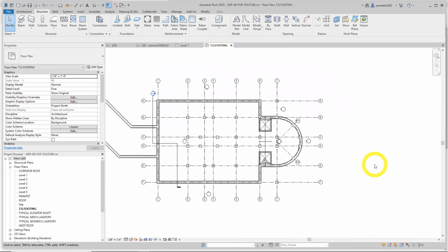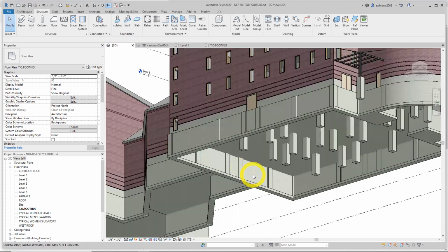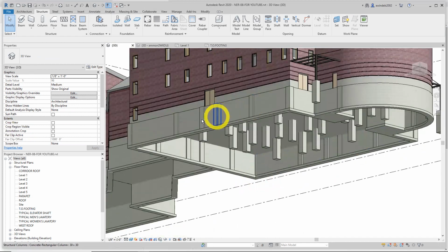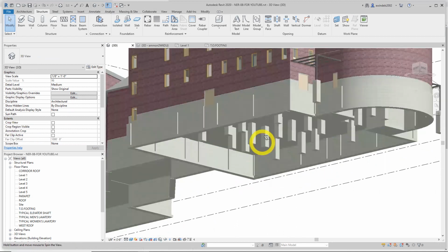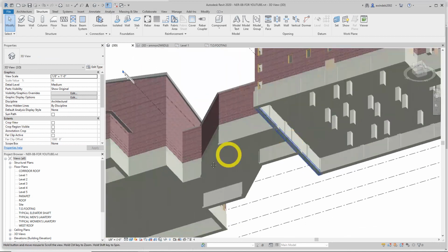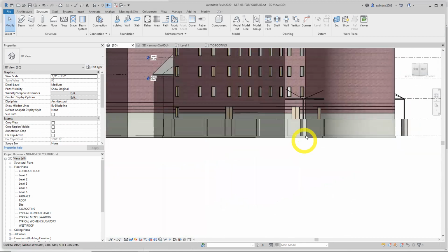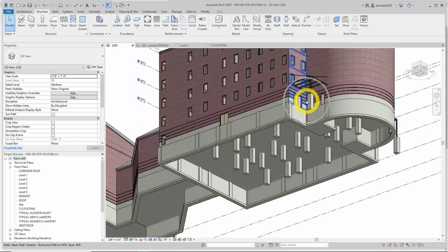Back to this floor plan, top footing. And this is a new command as well. We're going to add through the isolated foundation button little foundations, little footings on each of these piers. So you'll see them come up on the bottom of these. So we have our piers on the exterior wall and the interior points of the building on this side of the building. And also on our exterior framing we did earlier with some beams here.